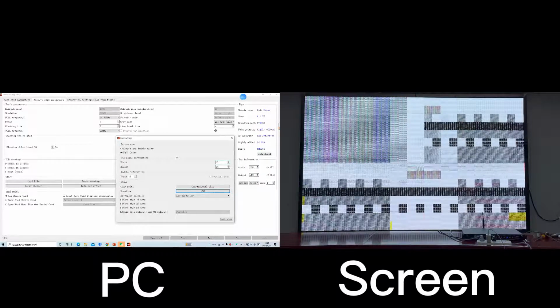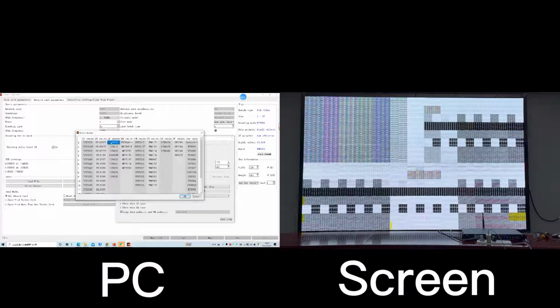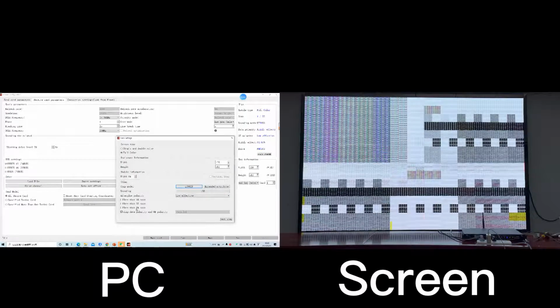We type in the right module information. This is a wire receiving card control, loading pixels, and we type in the module width and choose the driver chip ALS9927. We can keep the decoding chip at default decoding and choose more than 32 scan, because this LED module is 64 scan, so we need to check more than 32 scan in the first step of the smart setting.